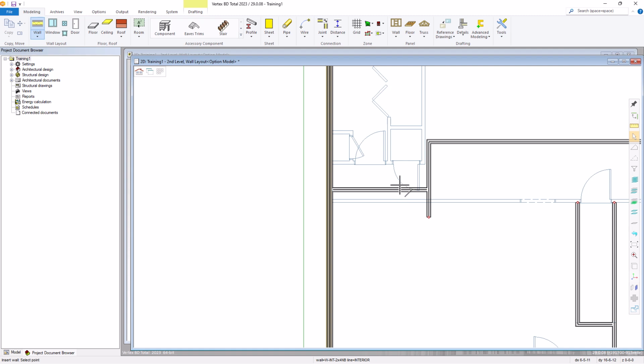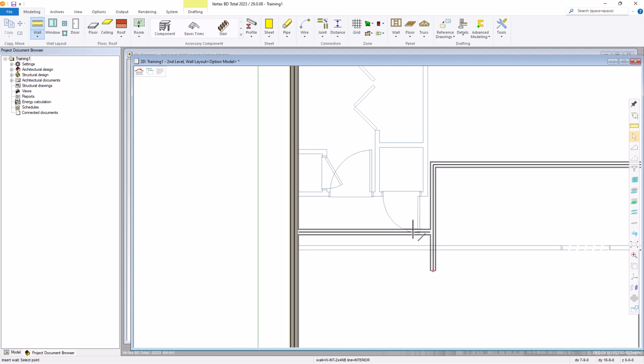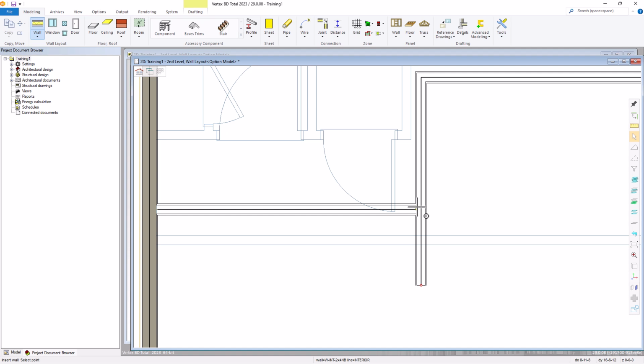And we have another wall. This is going to be a closet in here. So we're going to have a 2 foot 4 interior distance. We're going to go into this corner. Q. Select the letter I to lock it in the vertical. Type in 2 foot 4. And run the horizontal. So we'll hit the letter U. Change the offset to the opposite side. So that we have a 2 foot 4 interior distance. And we'll run that across. And hit V to confirm.